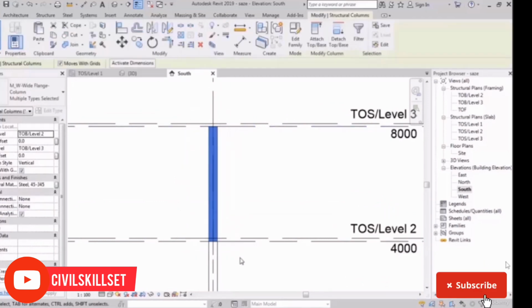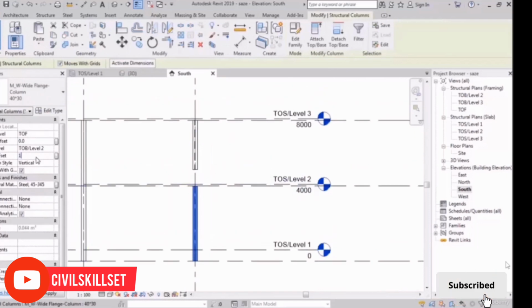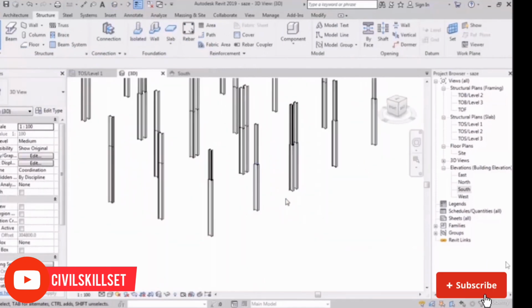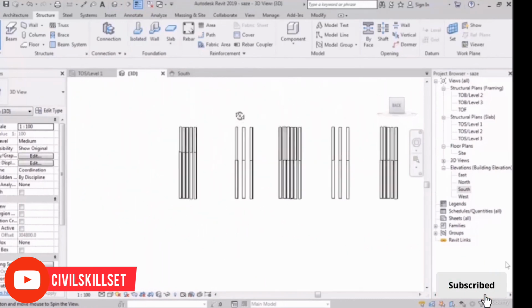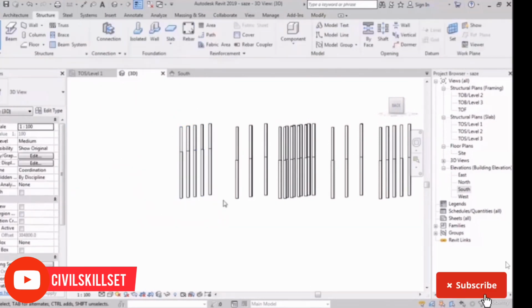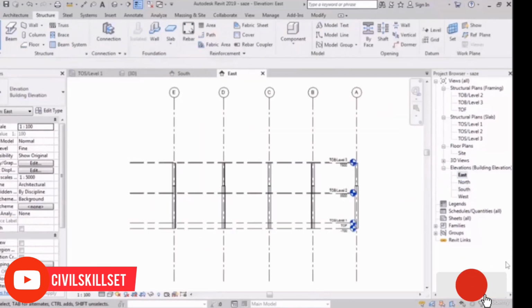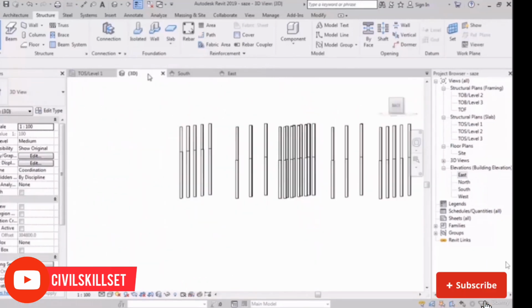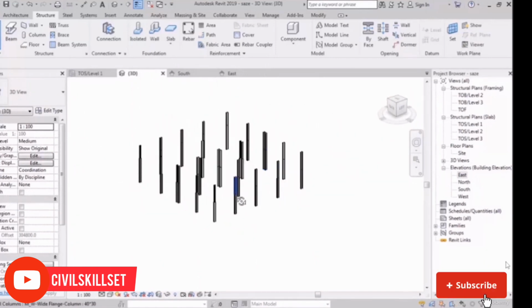Now, in order to do that in Revit, we're going to have to select these columns first, and then give a 1 meter base offset, and it comes up. Now I select the one at the bottom, top offset. Now it's so accurate. Let me do the other one too, where the size has changed. I'll select the ones at the top, positive base offset, the one at the bottom, positive top offset. Then we go to the elevation view. You see that? You will also see them later. So in this way, we can paste columns in higher floors, higher levels, and if their sizes change, we can also fix it. Well, this was everything about the columns.